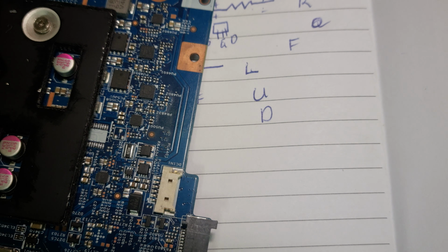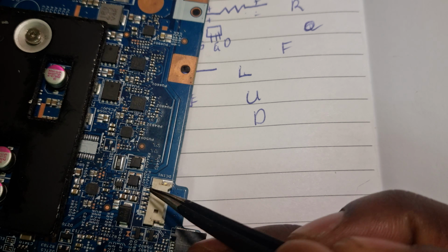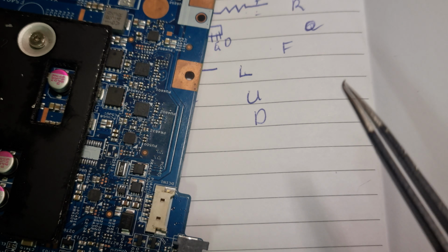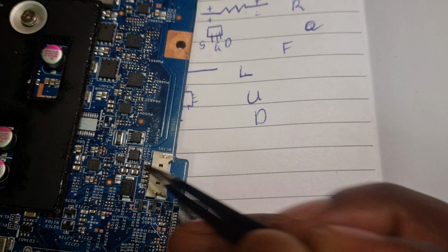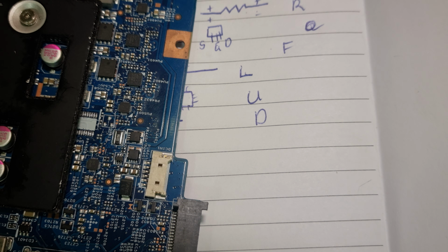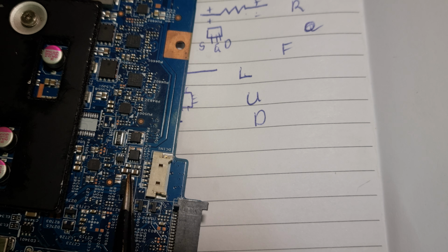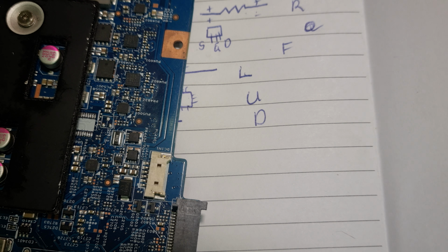If you take a look over here, grab a tweezer. You've got your charging port which comes through here. You've got your first MOSFET, your second MOSFET, and then your current sense resistor. From here, this is now a main power rail. But we've got this diode over here and these capacitors and that resistor. So this diode has been put in reverse, which means it has been put in such a way that if you plug a charger, power can only go from this side to this side. But if you put power from this side coming this way, it doesn't work.